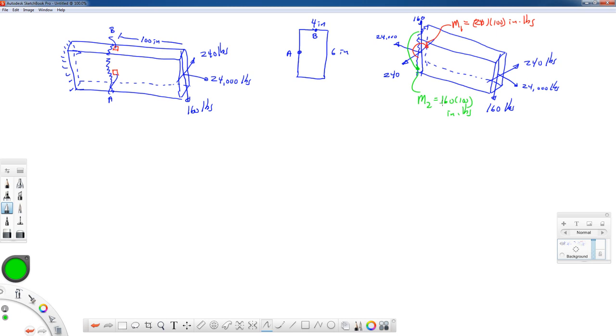Now, we don't have a torque on this structure. In our class, we haven't learned how to deal with torsion of non-circular cross-sections. So if you come up with a torque on a rectangular cross-section bar, one of us made a mistake. Either I made a mistake making the test problem, or you've made a mistake doing some of your statics.